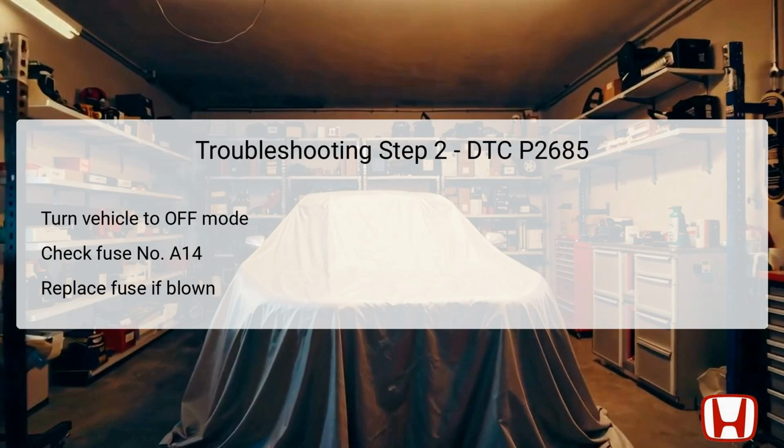Conversely, if the fuse is blown, it must be replaced and the circuit should be rechecked for faults. If the newly installed fuse blows again, this indicates a potential short to ground in the VB3 plus B TCU3 wire, necessitating further diagnostic processes to isolate and fix the short circuit promptly.